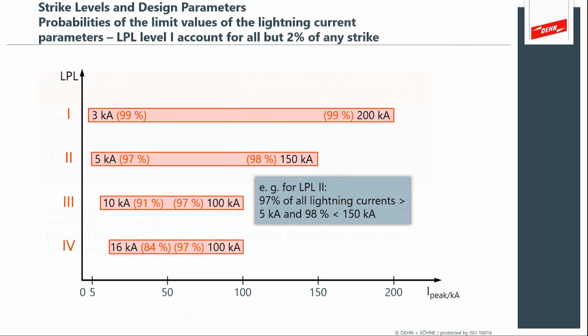And this is important because if you look at the range of lightning, and what's nice about this slide is it shows that 99% of lightning is greater than 3 kA, and 99% of lightning is less than 200 kA. And these come from the standards and the extensive research conducted by CENELEC and CIGRE. And there are some brilliant contributions from members such as Anton Rakov that look at how we can measure what's happening in lightning, and then you can create a distribution table like this.